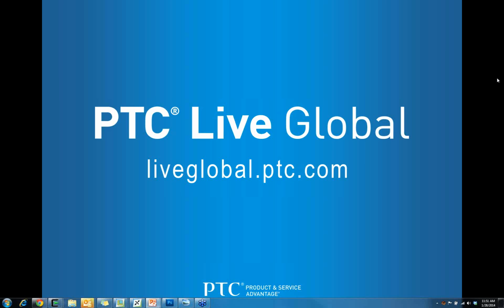The next question is, is Creo Direct 100% compatible with Creo only, or can it be used with Wildfire 4 or 5 data? So you can absolutely load in Wildfire 4 or 5 data into Creo Direct. Once you save it in Creo Direct, you can then no longer open it up in Wildfire 4 or 5. So everything is upward compatible, but not backward compatible.